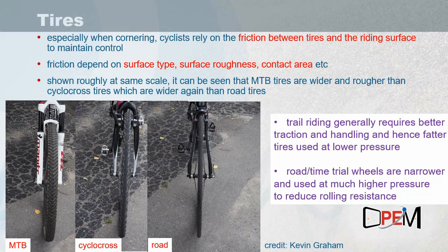In the case of trail riding, if you're riding in regions with lots of rocks and roots, etc., of course you want to avoid getting a flat tire, and so you are usually trying to balance between the maximal contact area between your tire and the surface you're riding on versus not having so little pressure that if you hit a bump with enough force, the tire will collapse and potentially puncture.